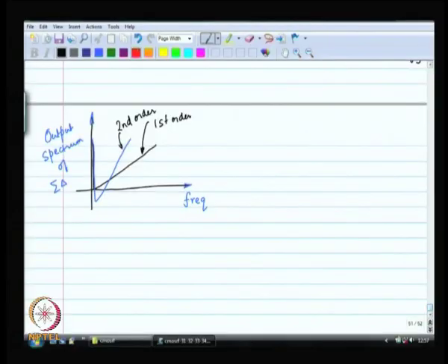So, as far as we are concerned, this x is a low pass signal, it is like a DC, it is a constant signal. So, really the signal to quantization noise ratio within the pass band can be made arbitrarily large if you just keep using integrators or accumulators as your building blocks.